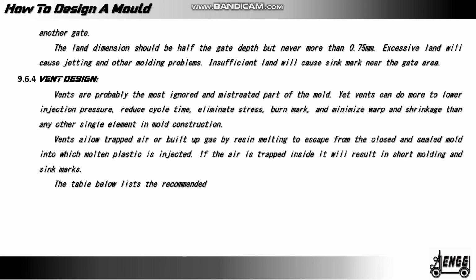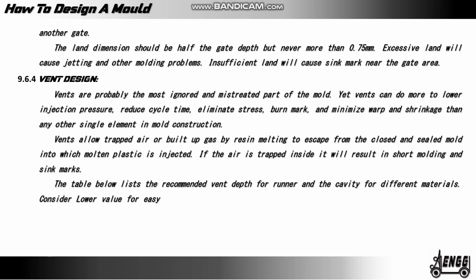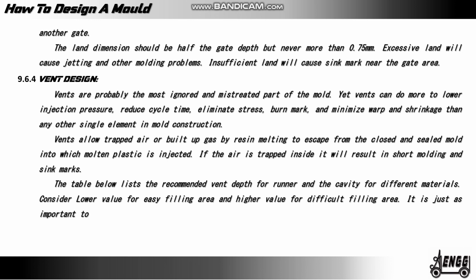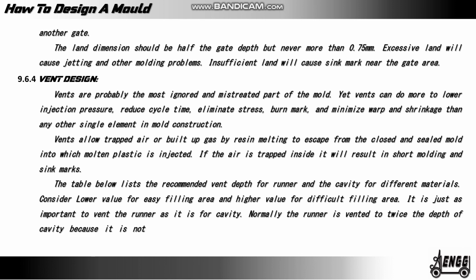The table below lists the recommended vent depth for runner and the cavity for different materials. Consider lower value for easy filling area and higher value for difficult filling area. It is just as important to vent the runner as it is for the cavity. Normally the runner is vented to twice the depth of the cavity because it is not a problem if there is a little flash on the runner. In fact, flash is an indication of proper venting.